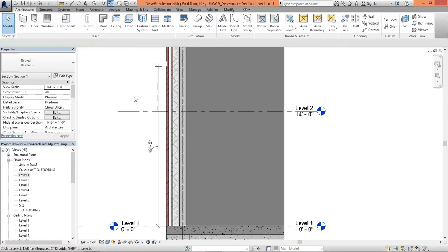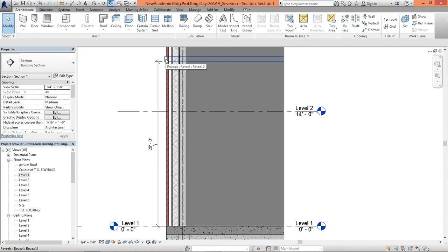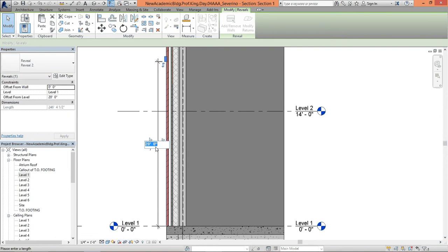There you go. So again, you select what you want to move and double click on the text. It's just that sometimes it's tricky. So this command, so you can set it to 20 feet, and what it does is move that element that you have selected previously. So again, select, double click, or click directly on the text once and say like 18.